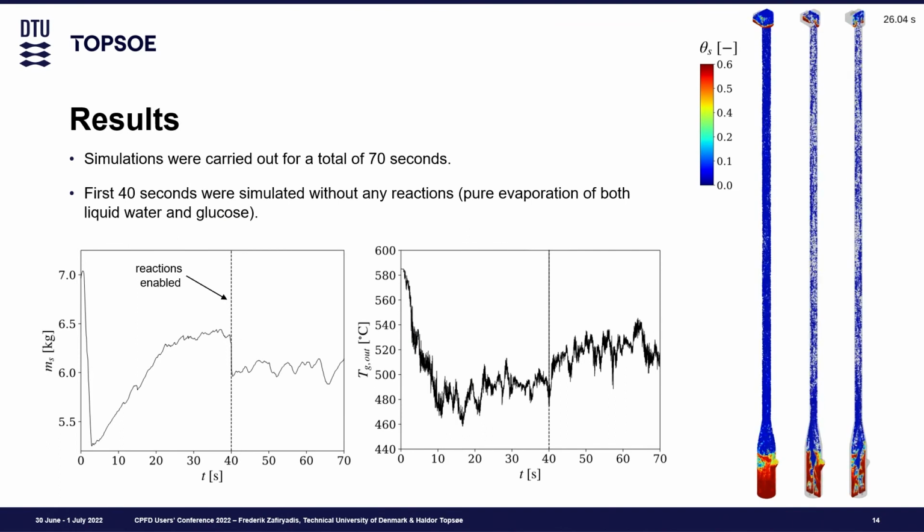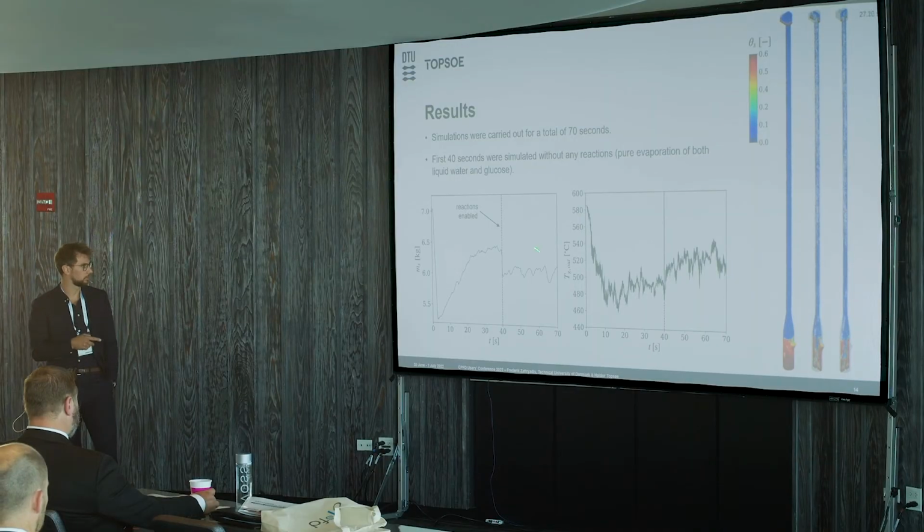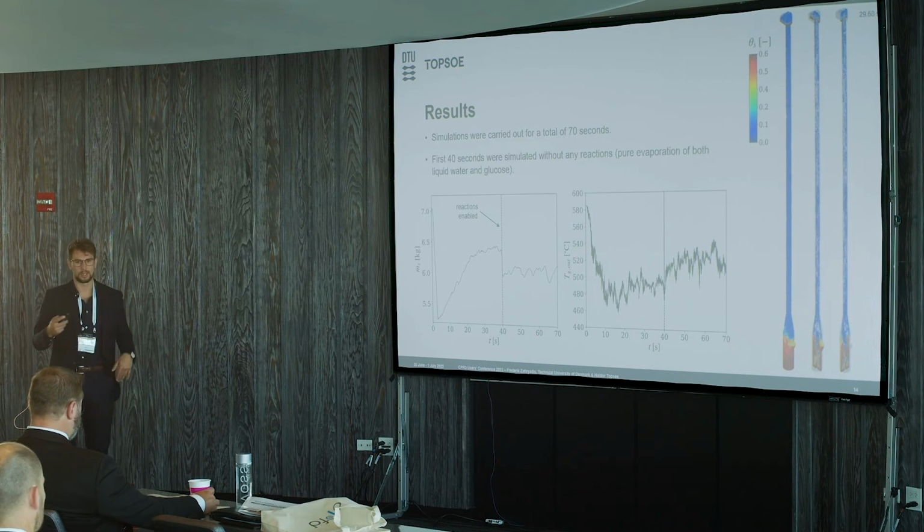So we took all of that and we combined it into one simulation. It's quite heavy with all the reactions in place, and we tend to get quite low time steps also with the high velocity injections that we get in the feed conditioning zone. So we started out simply by simulating the first 40 seconds using no reactions at all, and then use that as sort of initial condition for the further simulations, and then switch on the reactions here.